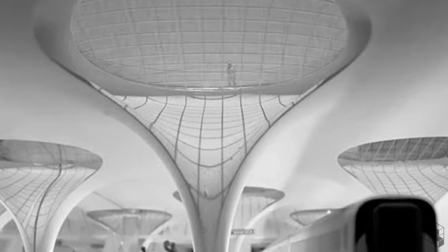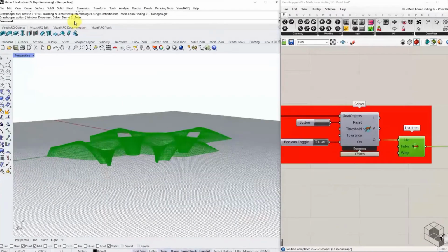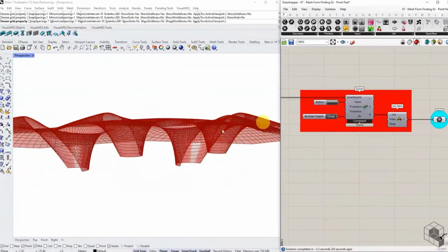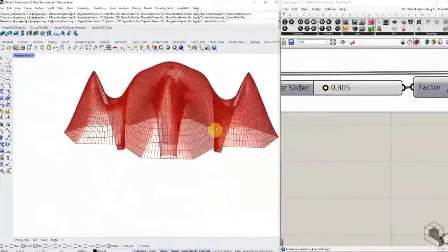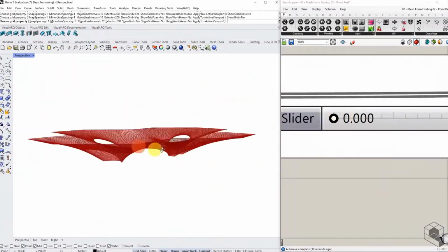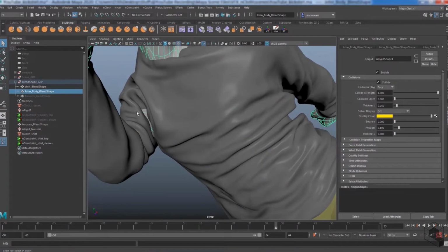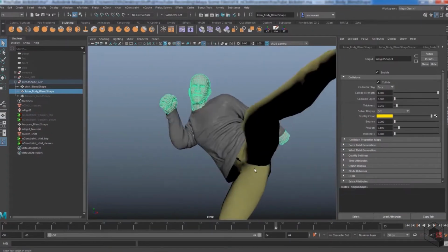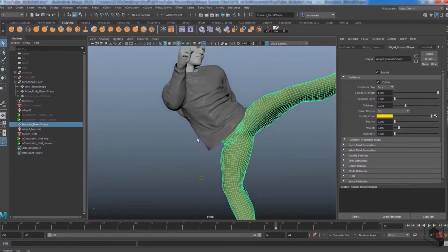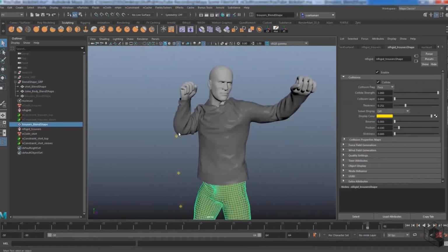Today, traditional form-finding techniques are applied digitally using particle spring systems that simulate the physical behavior of deformable forms. Initially developed for character animation and cloth simulation, particle spring systems created in software such as Maya, or more recently in Rhino Grasshopper or Blender, have emerged as powerful techniques for form finding.